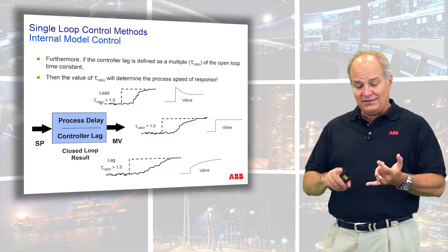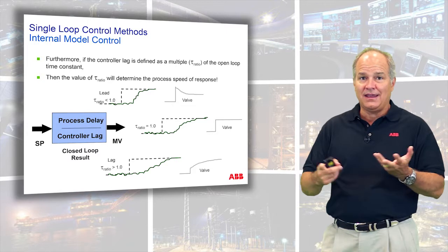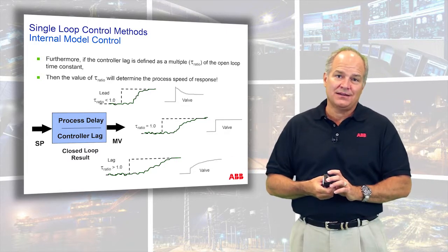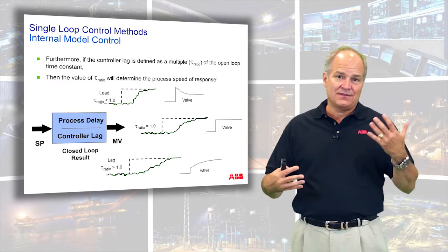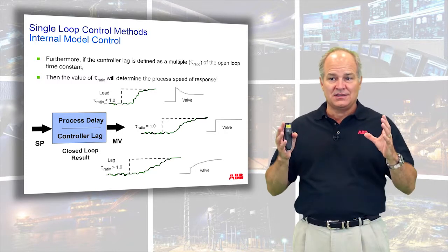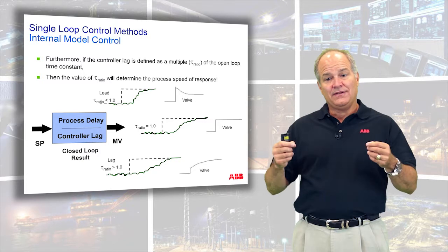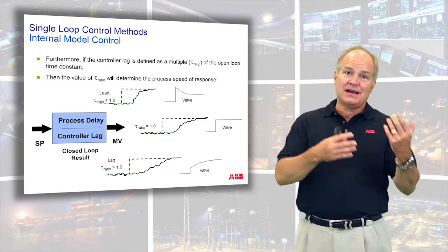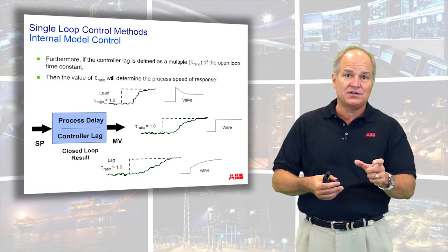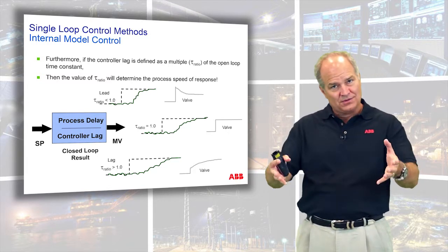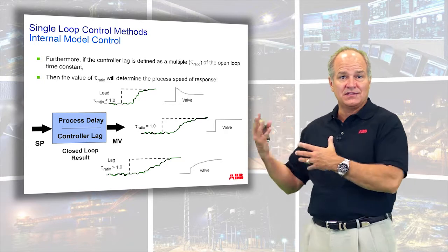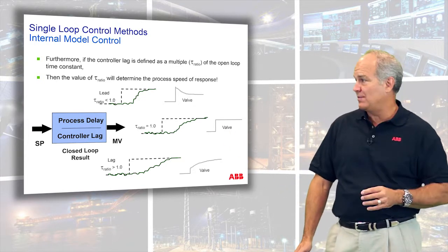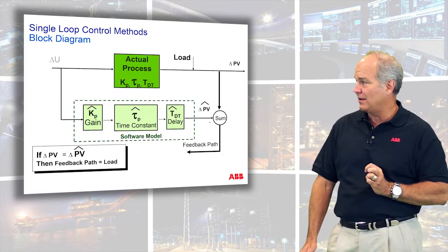But we enter the delay, the lag, and the gain exactly equal to the process model that we calculated. And that's the beauty, and that's also where it's tricky. Some of the internal model controllers, you have to enter all these parameters. Some of the model controllers, you enter the model and it calculates the tuning for you and you just enter the ratio. So you'll have to look at how your particular implementation is, but that's not so difficult once you map this to how your particular situation is working.